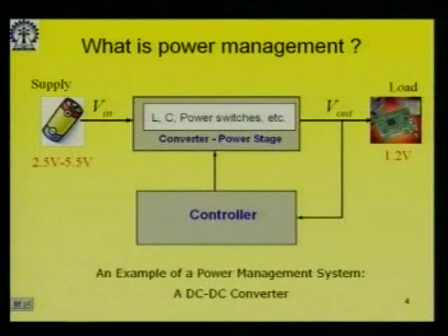It will be around nominally 12 volts, and then internally, as you know, all these latest mobile processors are operating at 1.1 volt. So again, from 12 volt you need to have a 1.1 volt output. So there are lots of stages, and at each stage there are issues like losses, how we can minimize the losses. And if we have losses, apart from the fact that the energy is going wasted, it also heats up the components and the area in the vicinity of those components.